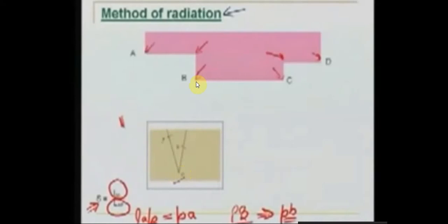Let's say it is 60 meters. Then I will convert this 60 meters into the scale. Let's say for the previous distance I had taken 80 meters equal to 8 centimeter. So here 60 meters will be equal to 6 centimeter. So at 6 centimeter distance I will mark a point, and that is my point B on the sheet.